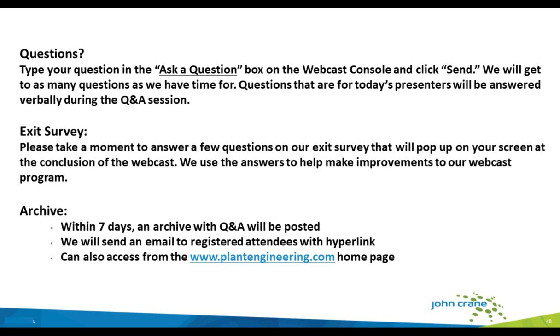about running dry indefinitely. And you also want to consider that in a real life dry running scenario, the seal faces not only lose lubrication, but they're still under a load, and they're going to be impacted. So what I would say is a more accurate statement is that diamond treatment withstands intermittent dry running periods, and the duration of those periods can actually be, and has been, demonstrated through very accurate testing. I know John Crane has done several in-house tests on intermittent dry running of diamond treated seal faces under load conditions, and has been able to establish some rather sound criteria on that topic.